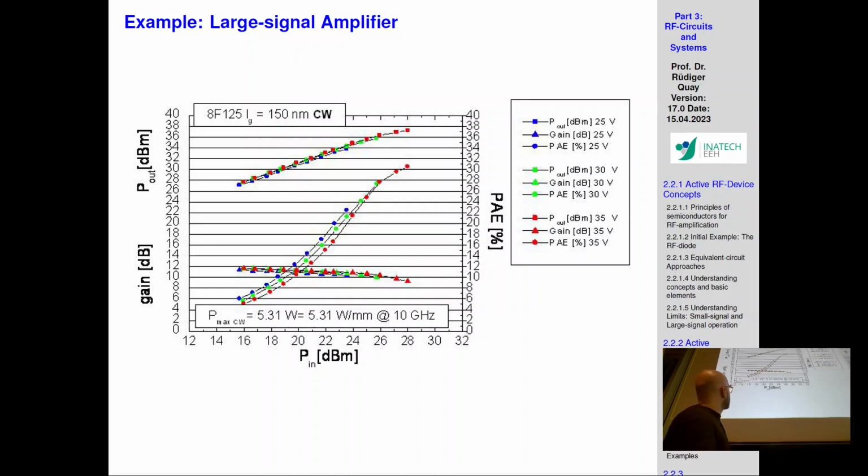This efficiency curve has lower efficiency at low input power, and as you increase your input power, you're increasing the gate voltage because you're increasing the swing of your input voltage signal. So you have a sinusoid signal that you're driving in. You're increasing the swing as you're increasing the power. This will obviously drive your device more into saturation. The higher you drive your device into saturation, the more efficient device you will have.